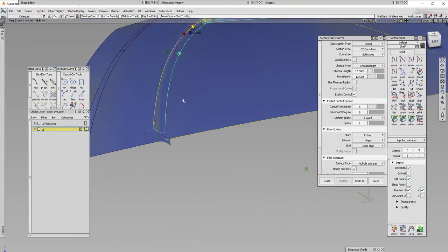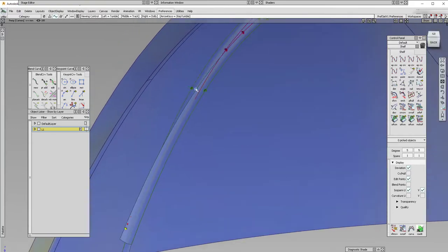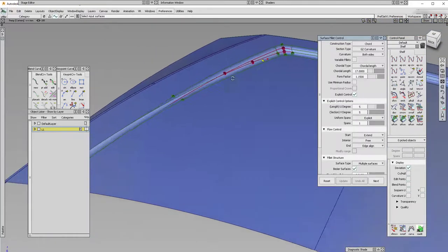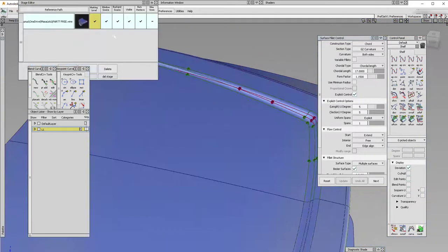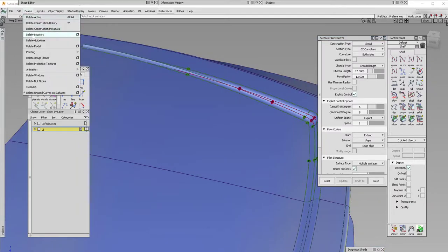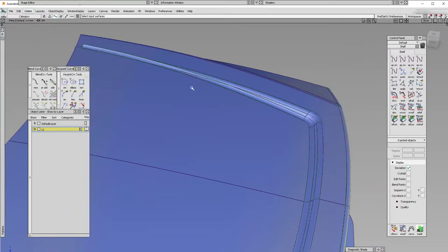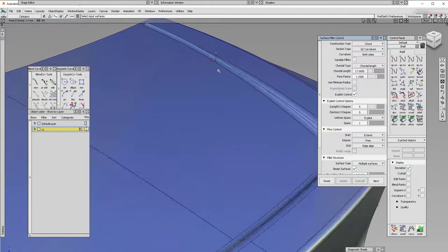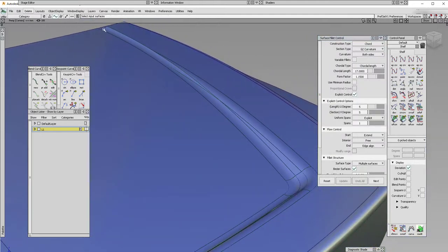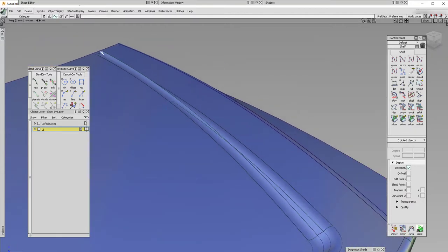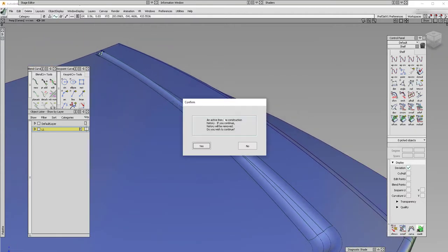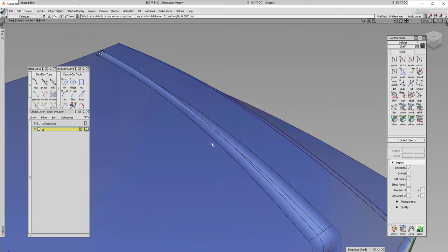And now what we're going to do, this is pretty much okay for now. Let's delete the locators. I am going to extend this edge of the fillets back until they are on top of each other. It says breaking the history. Let's say go, and Control Alt left click and sliding.